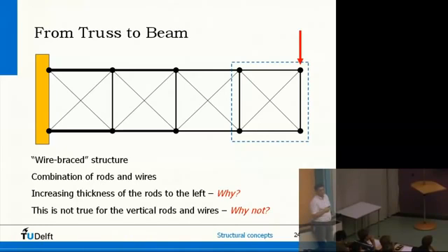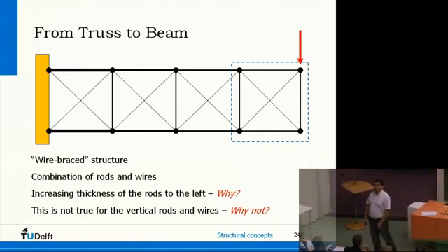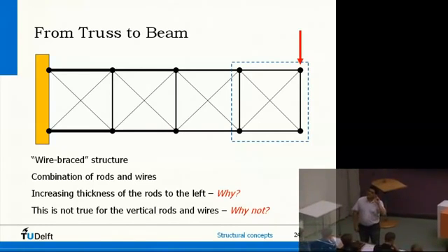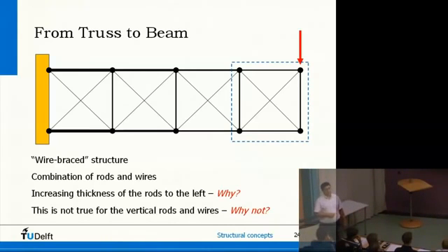Yeah, but what elements are transferring this force to the reaction forces here? The wires? Yeah? So this force is transferred to this wall via these vertical elements and the wires. And what is the size of that reaction force at the left side? Is it larger than my applied force? Smaller? It's the same size. It's the opposite direction, but it's the same size. Yeah? I hope it is on the next slide.